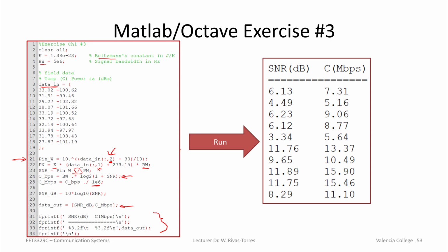And that temperature change is changing your noise power, therefore it's changing your signal to noise ratio, amongst other things, right? That might be impacting your signal. And so at the end of the day, our channel capacity varies daily due to all these circumstances. And you can see like the first 5 days, we kind of had a lower capacity than the last 5 days, right?